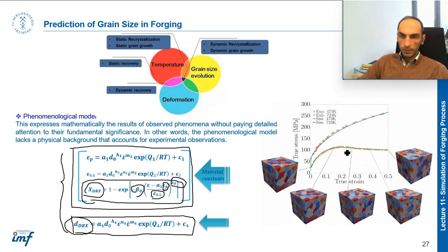It is the strain at 50% recrystallization. This is the peak strain, epsilon peak, this is the steady strain, and when the stress is exactly in the middle between the peak and steady, you can read the value of the strain as epsilon 0.5, or the 50% strain.